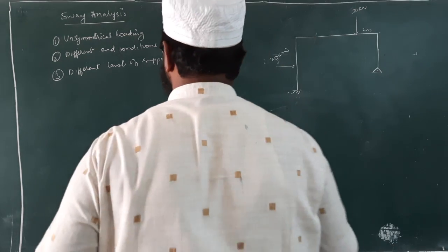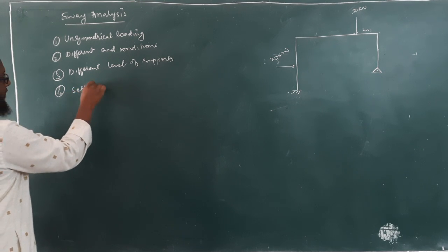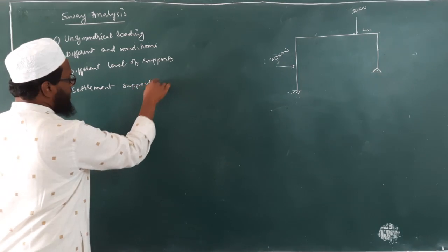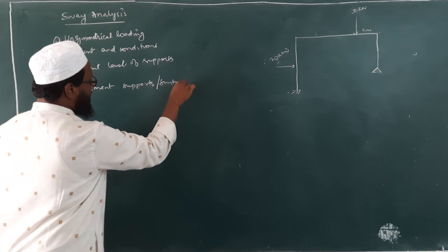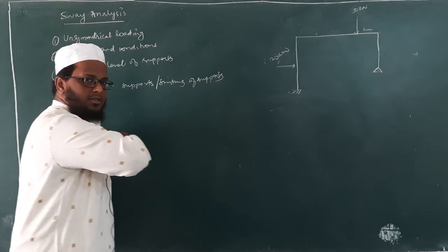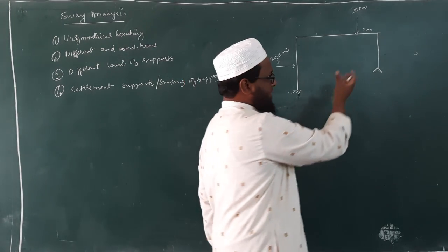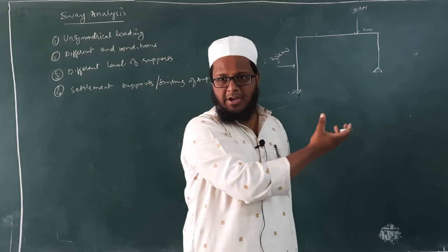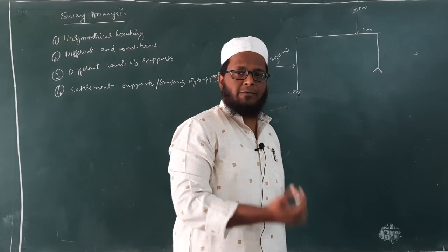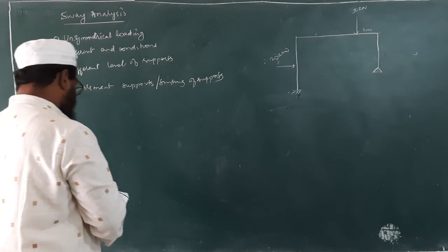Another thing, one more thing we can say is settlement of support. One more important thing, settlement of supports or sinking of supports. Suppose this point A sinks down by 10 mm, or support D sinks down by 10 mm, 15 mm, then again the frame will experience sway. So we have to perform sway analysis in that. How to perform that, we'll see. Okay. So take down the question.